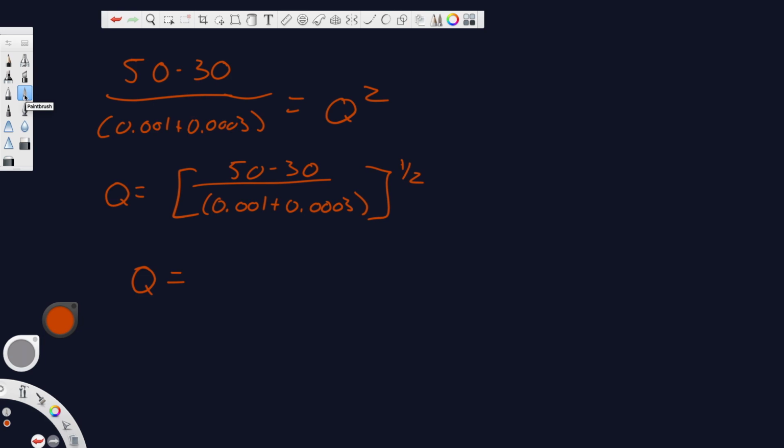So once you've taken the square root, you will have the solution of Q equal to 124 volumetric units, based on what the volume of Q was. Some typical units would be gallons per minute. And so there you go. It's pretty simple if you know how to set these systems up and find the intersection between the two curves.